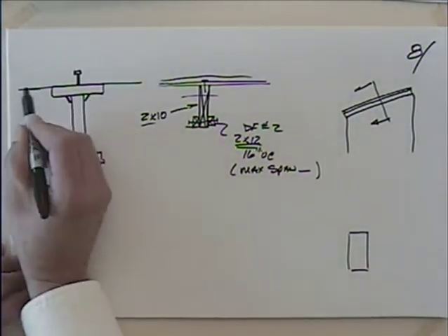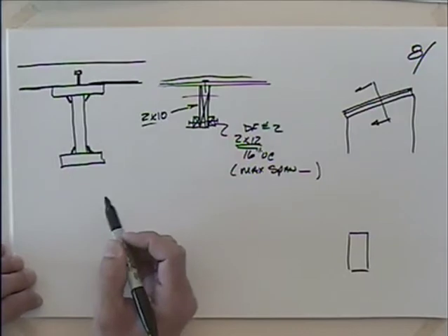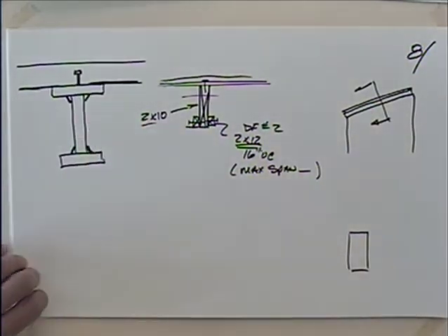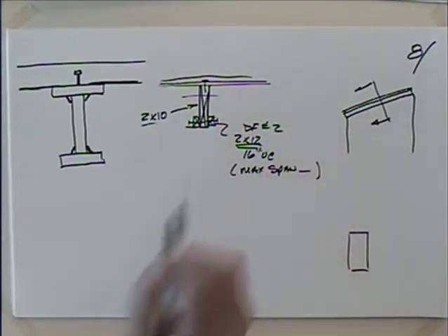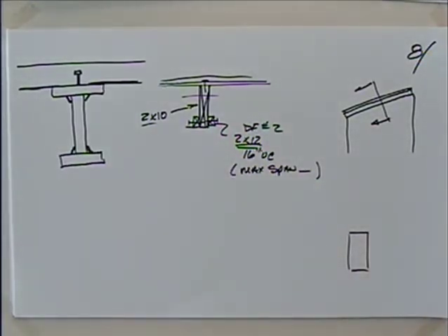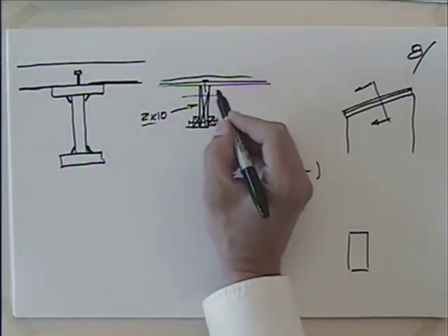They've got the I-beams, then they put this pan deck here. And then they pour concrete over this, and this stud transfers the shear into the concrete. So you get to have this thing acting like a composite beam. So I decided, well, I'd try that with the wood here. Okay? And it's a little dubious because your sheathing has breaks, and I couldn't make it work out.